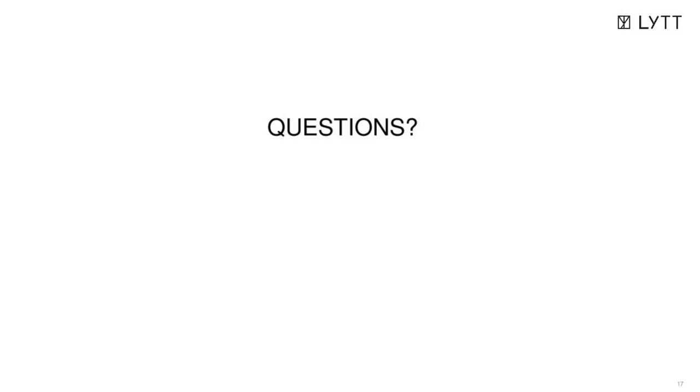Yeah, sure. So the answer is yes, we can. And that was one of the first examples that we showed today, where you can identify the sand entry point with some good precision. So indeed, you can use the DAS sand log to specifically identify the interval of sanding within meters. And the example that we showed is that this is key information in designing targeted remediation jobs, for example. Okay.